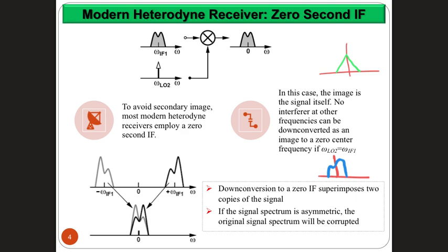Now what's being transmitted over the air is two signals superimposed on each other, and they have a phase shift of 90 degrees. That's exactly what a complex number is. Okay? And they are always orthogonal. At the receiver, when you multiply by cosine, you only get the cosine component, and when you multiply by sine, you only get the sine component. So they keep always being orthogonal to each other, and you can always separate them again.